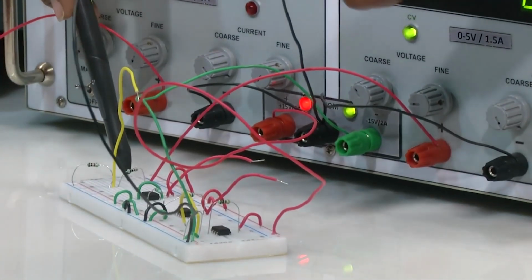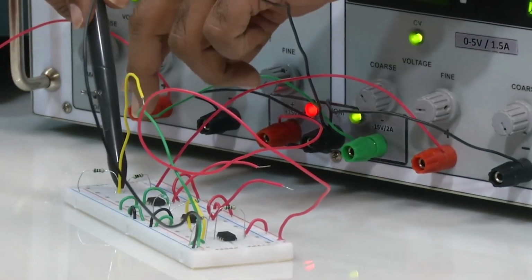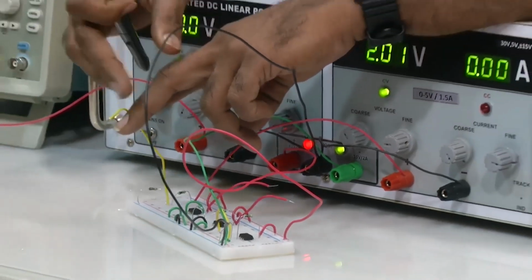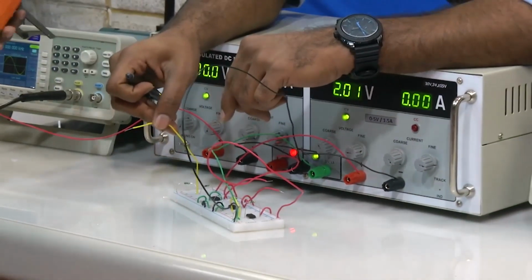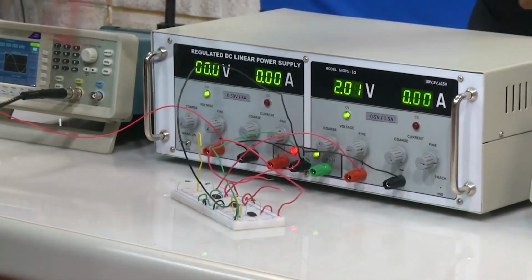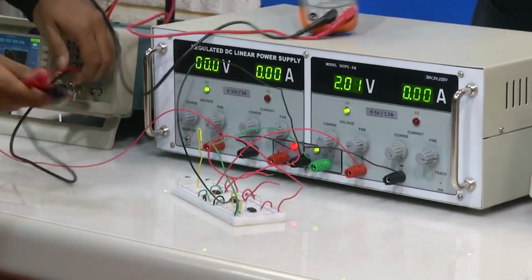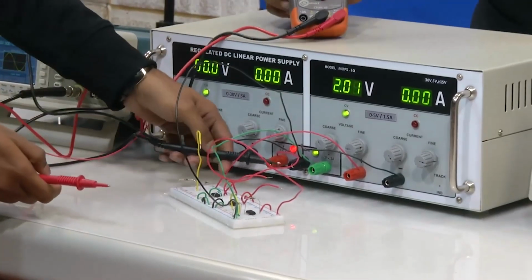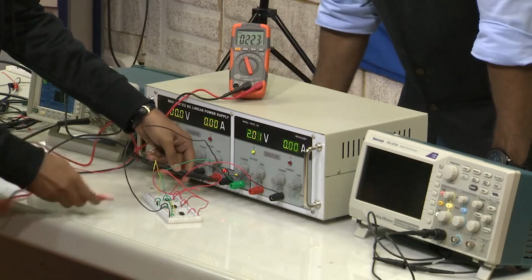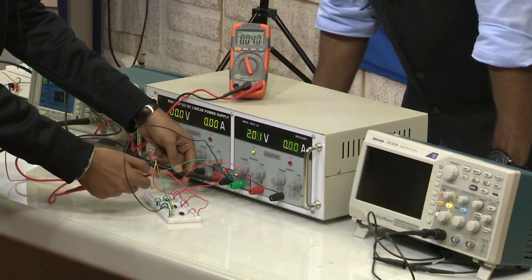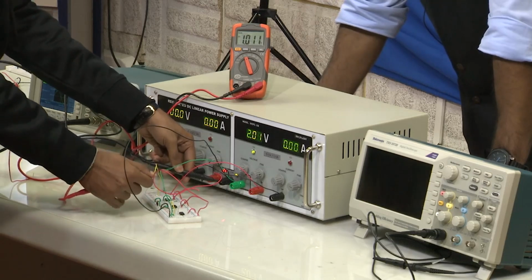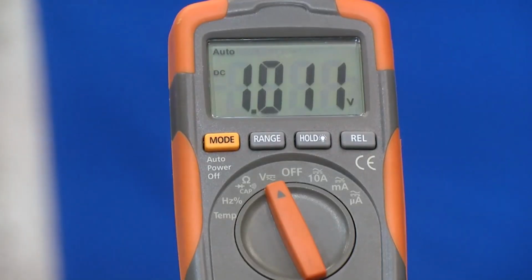What do I want to measure? I want to measure the value of voltage across R2. So, I have this yellow color wire. I will connect it to the multimeter and ground to ground. So, let us see. When he connects the ground and yellow wire, what do we see? We see output approximately half of what we have applied at the input,